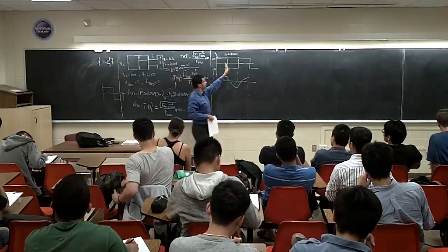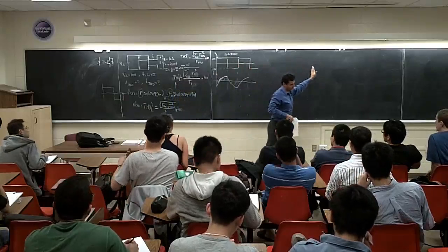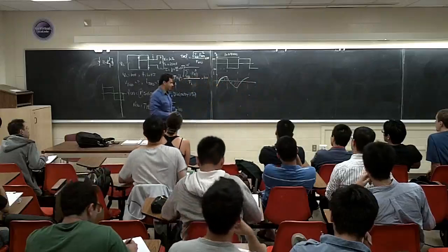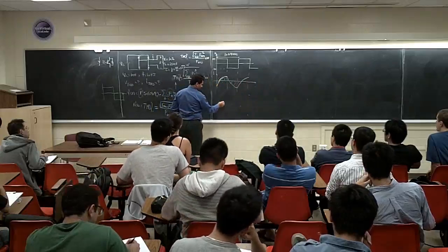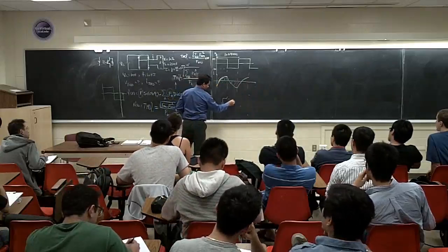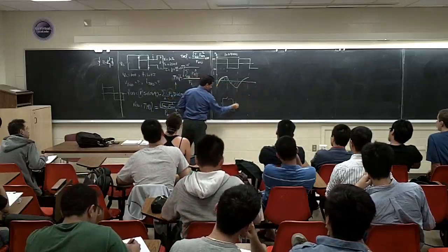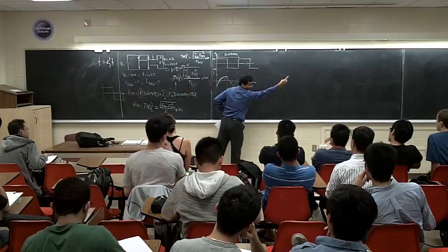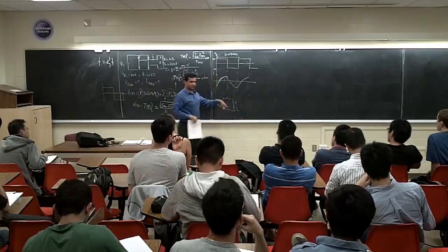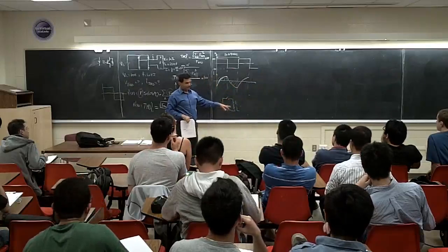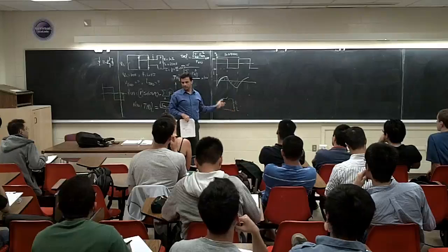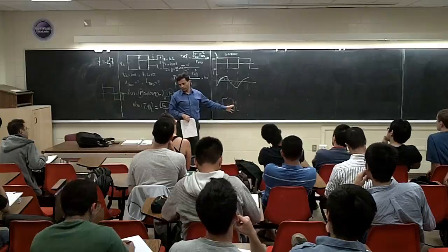If this one was very long, divided by R, right? If you have an RL circuit like this, it will be something like this: RL with VDC. I'm saying if this one was very long, when you close this switch, at the steady state the inductor is like a short circuit. The current in this circuit is going to be VDC over R.